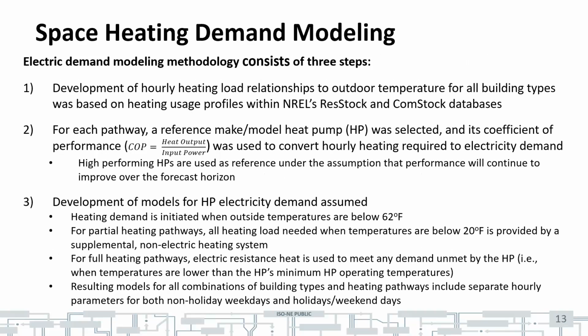In terms of the demand modeling, this is something we were very interested in. Basically, we want to develop first the hourly heating load relationships, as a first step, to ambient temperature for all the building types, leveraging the heating usage profiles in NREL's ResStock and ComStock databases. So for each pathway, they selected a reference heat pump.